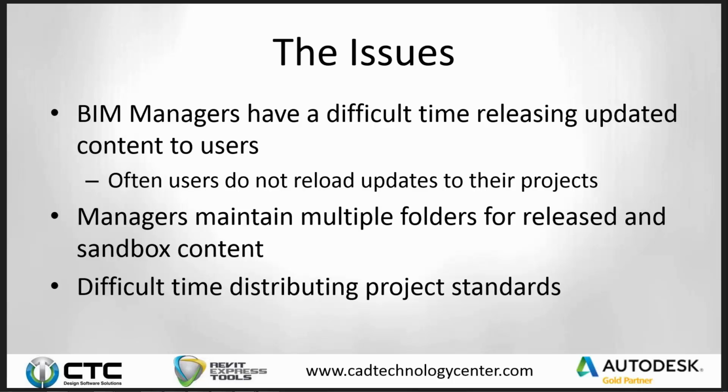Unfortunately, users don't often reload updates into their projects. But if you can train users to consistently use BIM List as their source for dragging and dropping content in, as they drag and drop it in, they can always have the latest version. So if there's been an update, it just reloads that update into their project. Of course, if it causes any problems for whatever reason, you can certainly work with them to figure out what issues might exist and resolve those. But they would have those issues anyway if they were loading new content in. This way, you're just finding it earlier in the process instead of later, when it's much more detrimental.